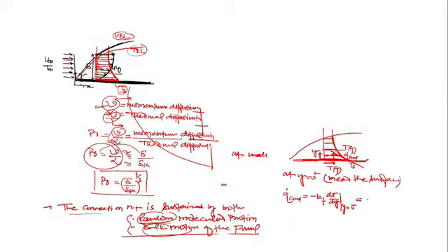Yes, so that's why I should write here h into Ts minus T infinity. So why have I not written A? That's because I write flux, and this is what the convective heat transfer is given by Newton's cooling law. Before this, you should write one point I just missed: the rate of heat transfer by convection is given by hA into Ts minus T infinity.